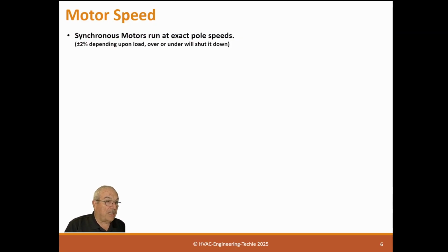Power comes in, it's cycling on the stator, and that's providing a cycling magnetic field. So the poles are changing magnetic fields from positive to negative continuously. And the rotor with DC on it will actually follow that cycling. It is the way they're made, it follows it exactly. So if it's an 1800 RPM motor, the stator's locked in. Basically, it can't get away from that magnetic field. It's locked into it, and it will turn at exactly 1800 RPM.